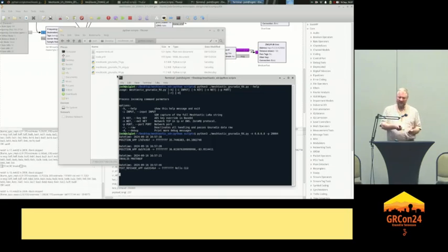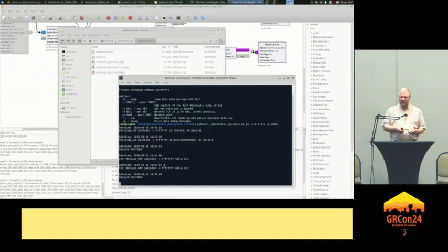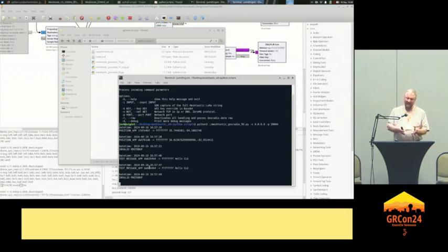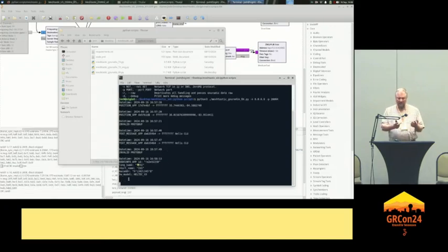And as we see here, we have messages coming through, and we can see some messages don't decode properly. Part of that is because I do have CRC errors passing through turned on, so I do get some errors in there. There's also some protobufs, which is further down the data pipeline that I haven't implemented all the way, so some of those aren't being parsed correctly. But again, we have a full stream of all the different messages that we see on the network right now. Now this is, like I said, just the receive flow. There's a node announce message right there. And then we also have the transmit code as well.